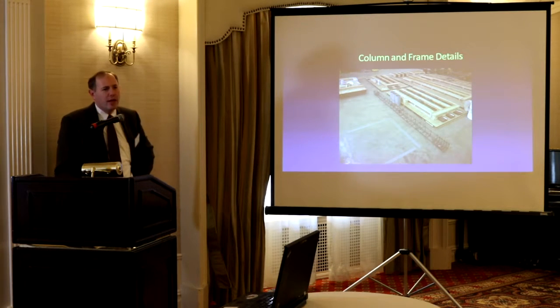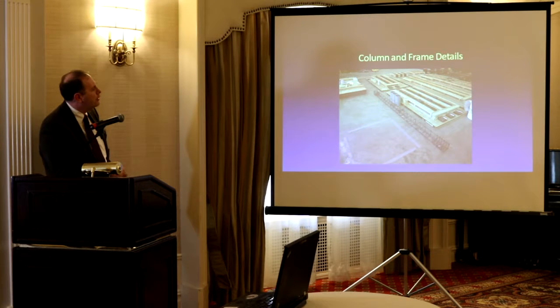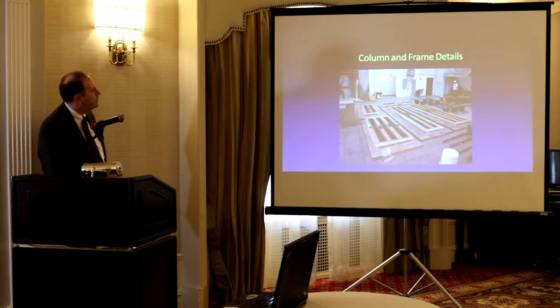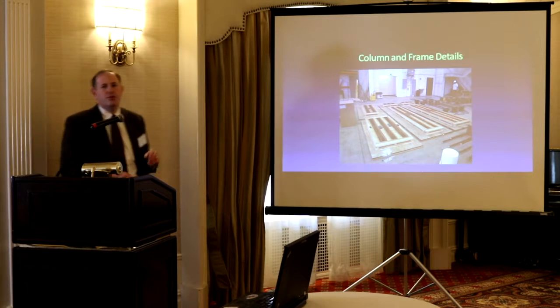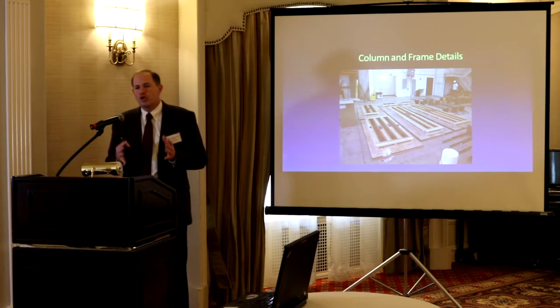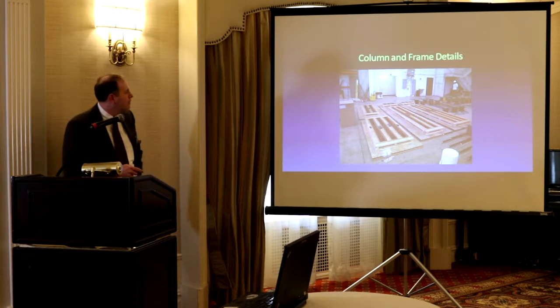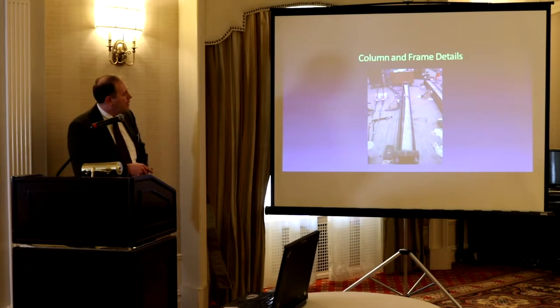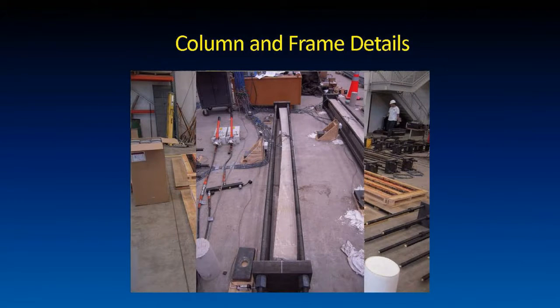Here's some images of the lab when we're casting them. So these are the different columns, and you can see some, of course, you can see this relative to the cylinder there. You get a little bit of sense of scale. They're reasonably sized, and then we have our ties. So here's the bed there before. You'll also notice we did some short columns too. We calibrated some of our creep and shrinkage that's occurring relative to short columns that didn't have second order effects. And here's one of the columns, and this one is under sustained load at this, and you can see that displacement. You probably don't want that in your building, right? Or it could be interesting.